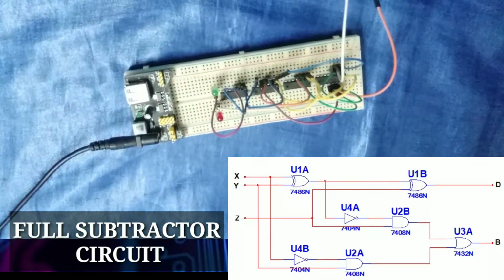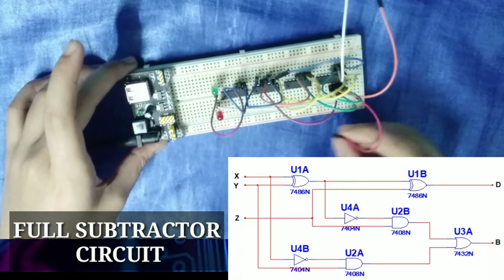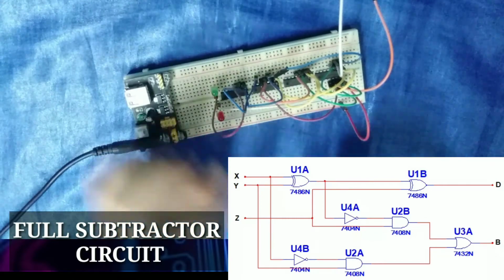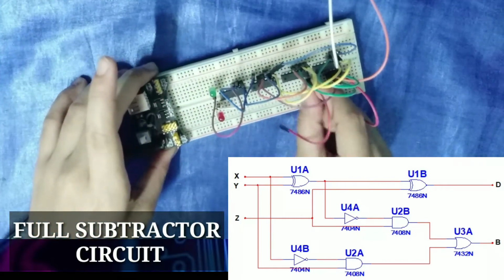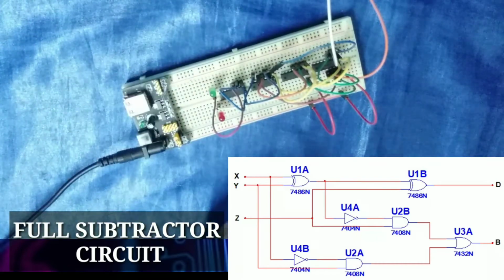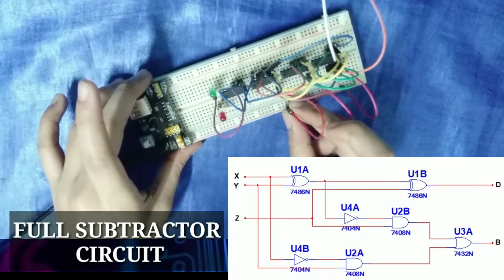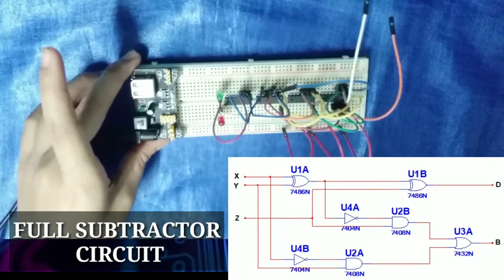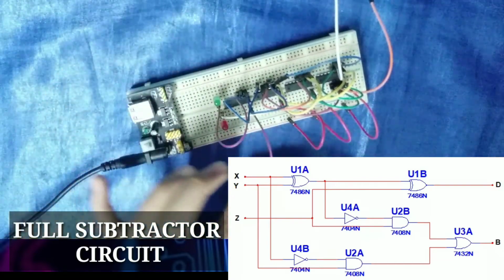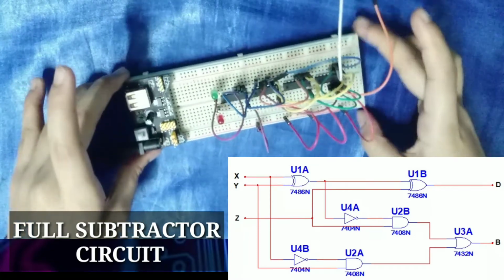And now, the most important part is the connection of our VCC. So don't forget to put all VCC connections to our integrated circuits. So in total, it will be 4 red wires to our VCC. Okay, and the last will be here on the 7432, connected to the 14th pin of the 7432 for the VCC.